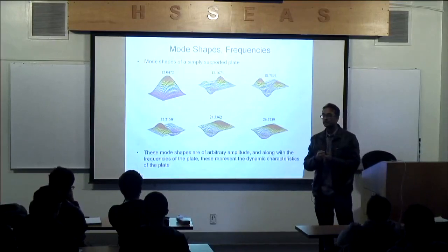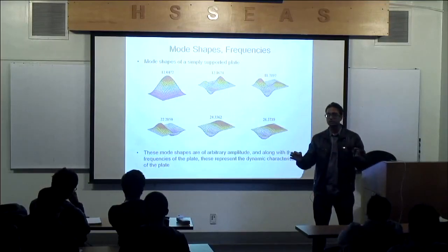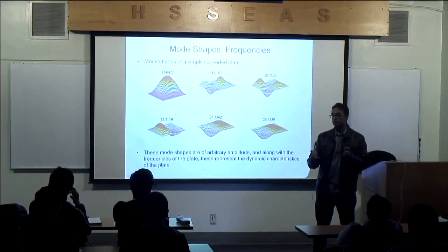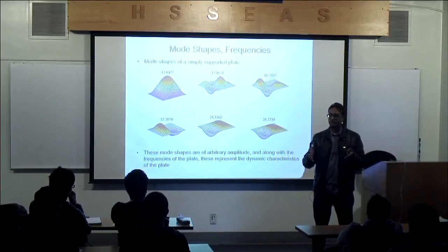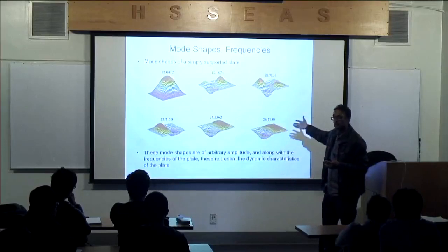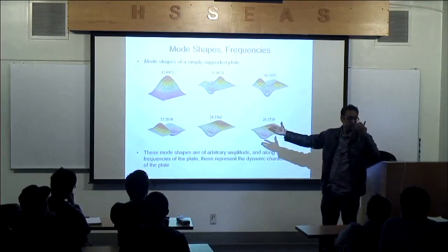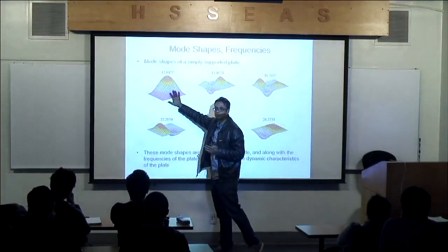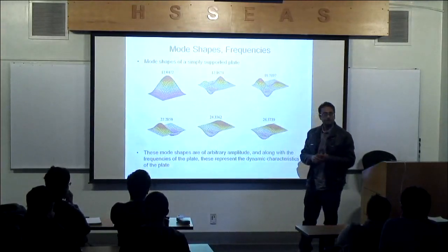That will then either excite particular modes during an actual application, or it could be that the structure is bending back and forth due to a combination of these modes. Can you imagine that for a linear system, the deformation of a system is comprised of a combination of these? You follow me? For example, a plate could be bending in a way that comprises the summation of this mode and maybe this other mode. Okay? Yeah? You follow the concept?